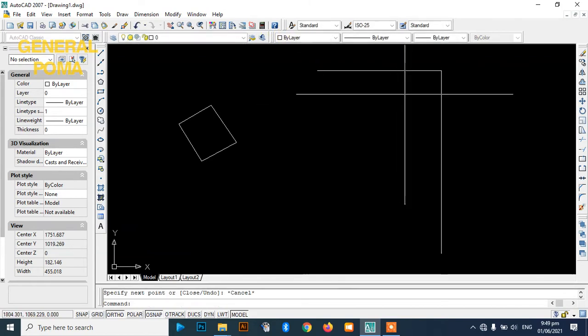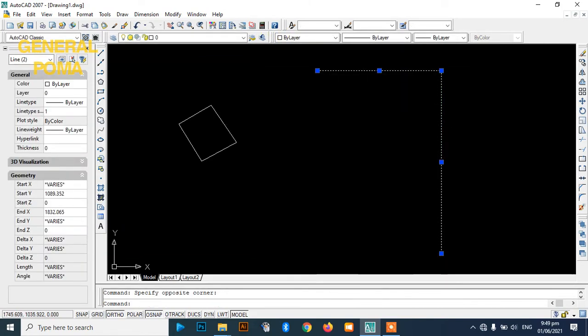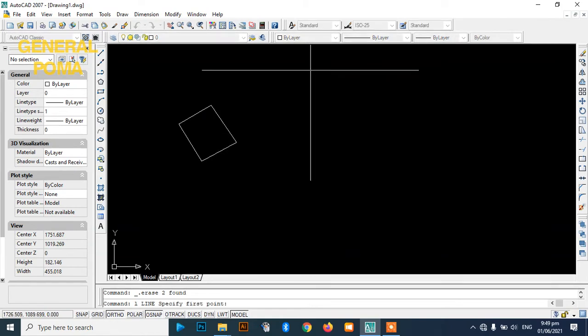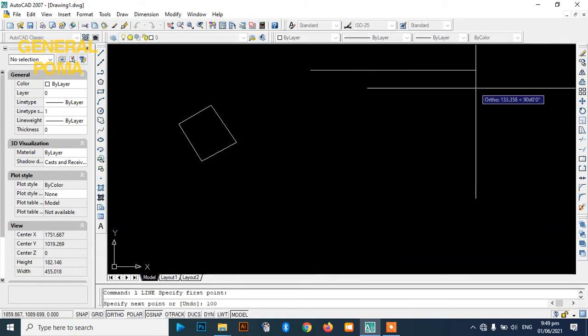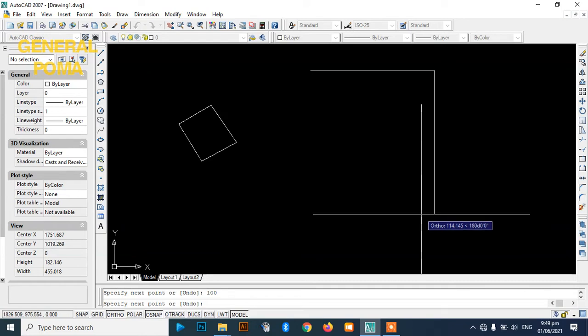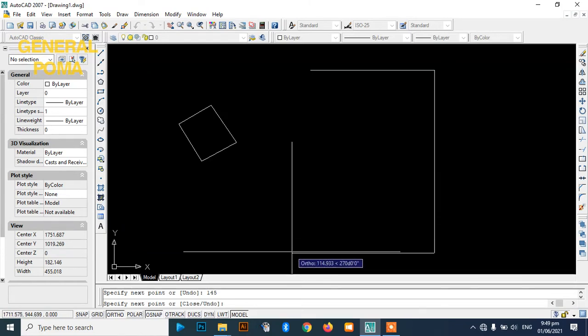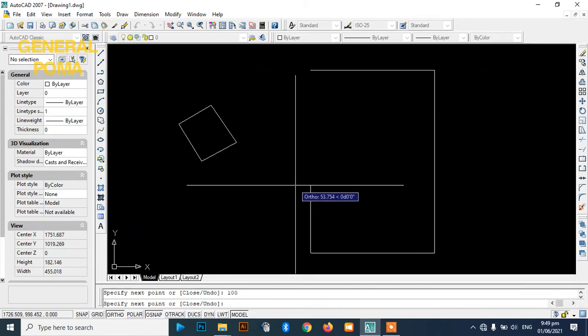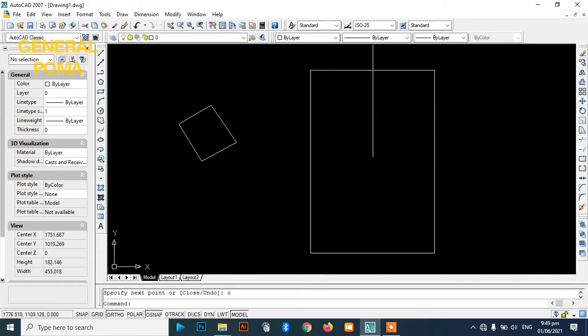Oh, there's a mix up here. Let me delete it and start again. Line, 100, enter. 145, enter. 100 again, enter. Then close, C, enter. So this is it now.